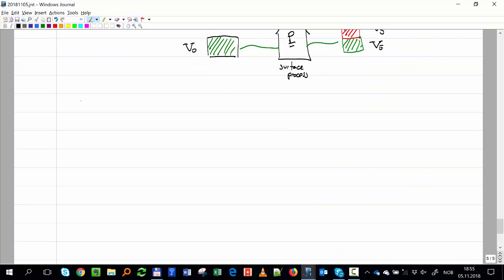Okay, let's go to the phase envelope of a gas. If I'm reducing pressure, in this case keeping temperature constant, it might be that I never have condensation of liquid, because simply the pressure is just too high. I'm outside of the envelope.